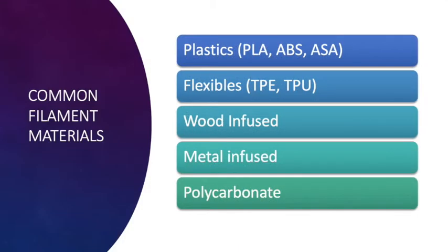And then lastly, polycarbonate. That's on the more expensive side of printing materials, but it's super strong. That's probably what NASA is using. I don't know for sure, but if I had to guess, that's the one they're using, because it's a super durable material, great under a lot of heat, just overall very versatile. So those are just some different things that they'll print with. In the Genesis Lab, we tend to use PLA just because it's cheap, it's recyclable, and it's convenient to have. It's very easily accessible all across the interwebs.